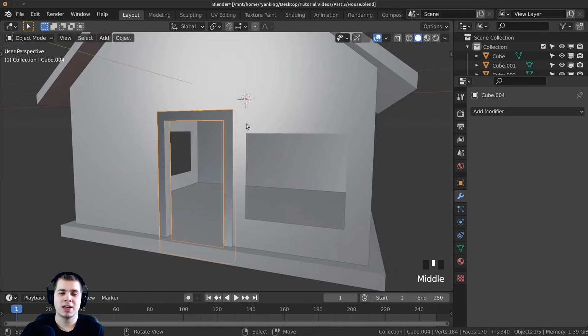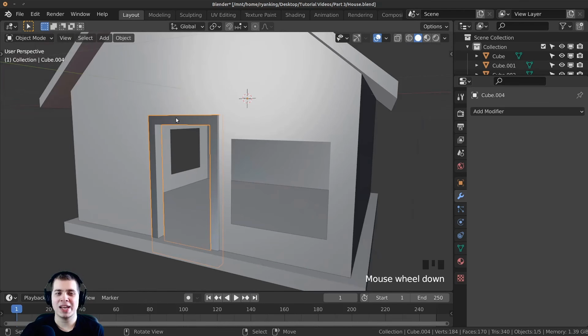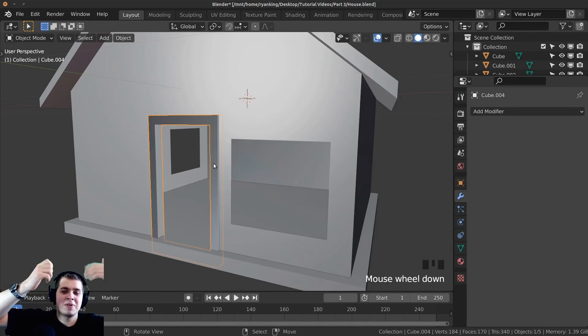But back to what I was talking about, this here is really white, and then this here is kind of dark. So what's actually happened is the mesh is flipped inside out. If you imagine like a shirt or a sock or something and it's flipped inside out, you can sometimes see the seams, or maybe you can see the tag. And so the mesh is actually flipped inside out, and so we want to flip it back. It's really easy to flip it back.